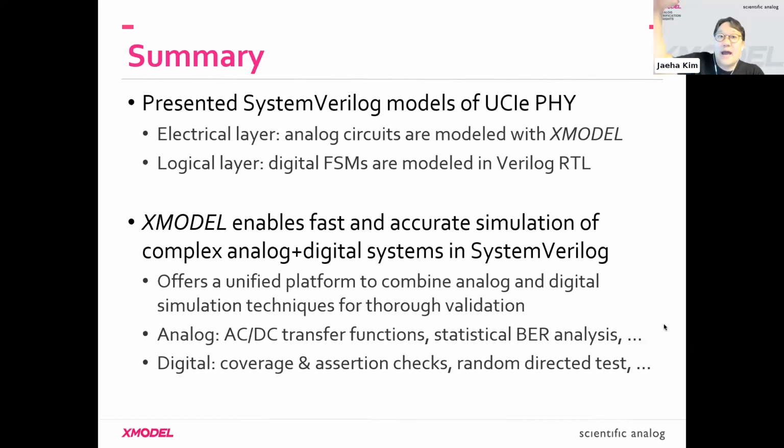For example, we had a D to A converter, the DAC primitive between the digital code and the actual weight that goes into the interpolator primitive. So that can have a non-uniformity. So that's one way.